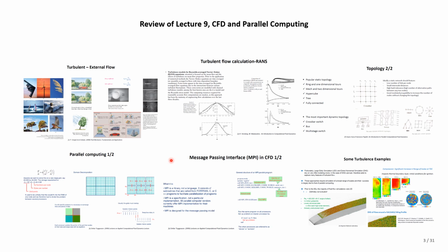And here we presented how you can use MPI to run the CFD code. In the final section of the course, we had an example of turbulent flow from a research study, and why in some problems it's essential to solve the problem via LES or DNS, and parallel computing is required.